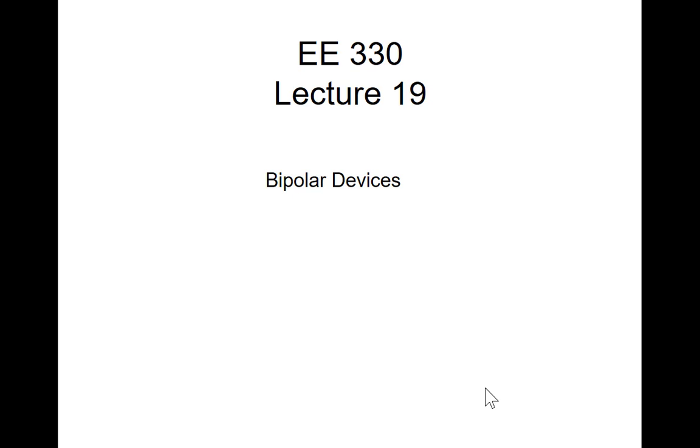So for example, on that process we looked at last time, did we put metal under poly 1? No. The reason we can't put it under poly 1 is that metal went on after poly 2. So when you look at that process flow, you'll know what you can put together and what you can't put together. And if you don't know that process flow, it's impossible to know what you can connect and what you can't connect. Does that make sense? Okay, so that's the reason I think we need to know the basics about a particular process flow.